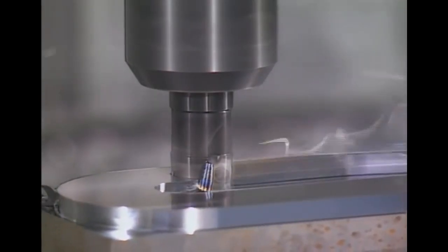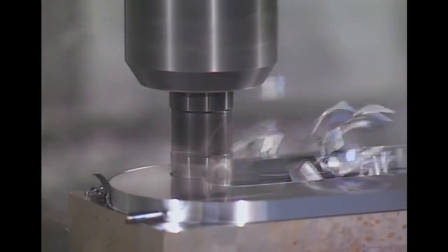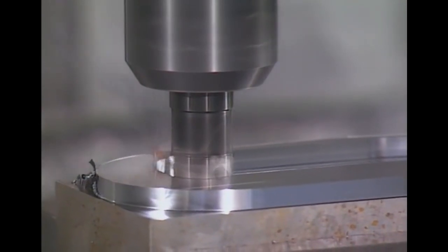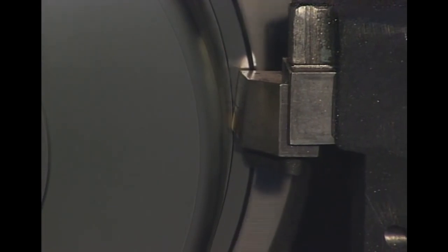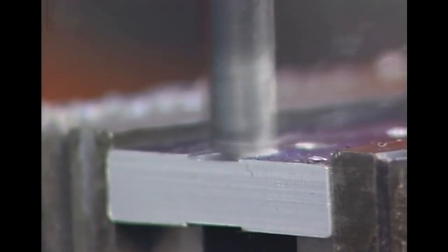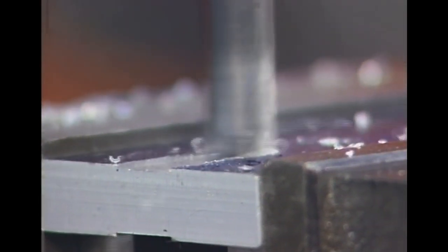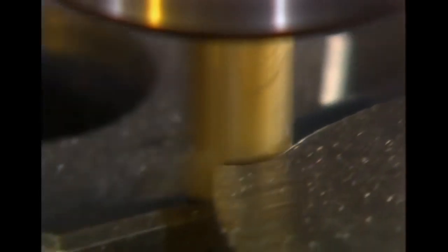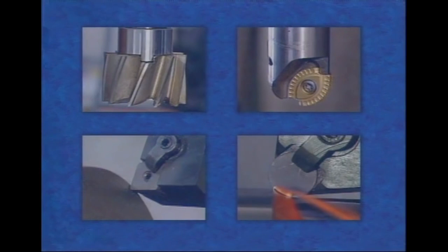Every new and established tool material has an application area in which it outperforms the other cutting tool materials. Newer materials tend to minimize but not eliminate the application of older materials, such as high-speed steel. The development of cutting tool materials has offered steady advancement in the rate of metal removal and, consequently, in the need for more heat-resistant materials. So there has been a progression from high-speed steel to carbide to ceramics and onto other super-hard cutting tool materials.